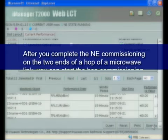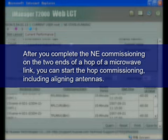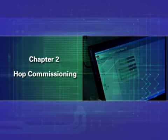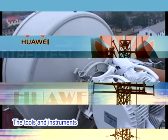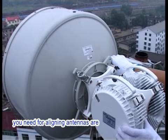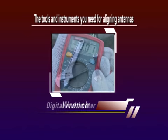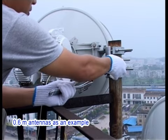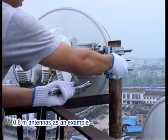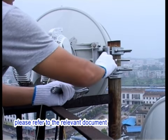After you complete the commissioning on the two ends of a hub of a microwave link, you can start the hub commissioning, including aligning antennas. Chapter 2. Hub Commissioning. 1. Aligning the antennas. The tools and instruments you need for aligning antennas are BNC cables, digital multimeter, and wrench. The following operation considers aligning 0.6 meter antennas as an example. When the antenna is of a different diameter, please refer to the relevant document.